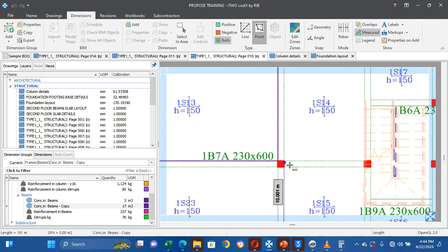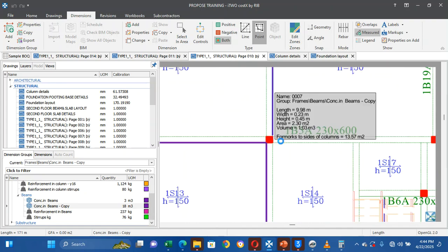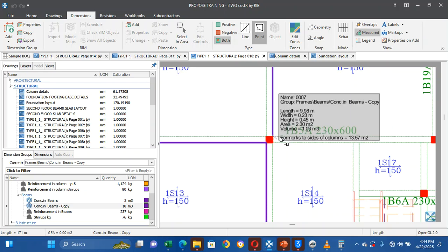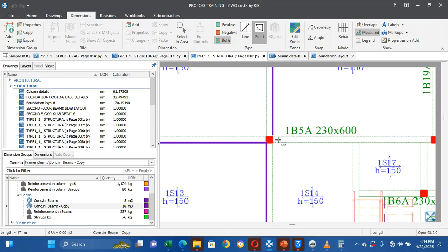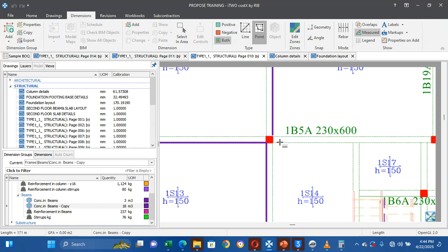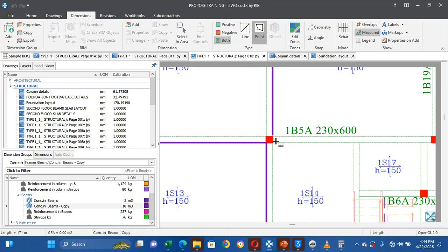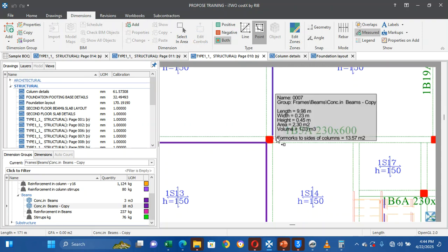To where? To here. Beam. Okay, so there is one thing. If I don't want it to join with this one, I don't want it snapping like this, then by holding O on the keyboard, it will allow you to select any point, even though you are close to this dimension that I have measured before. So let's see the point I want here. For you to stop this, just press O and it is gone. Then you click on your first point, then you release O. Say click.